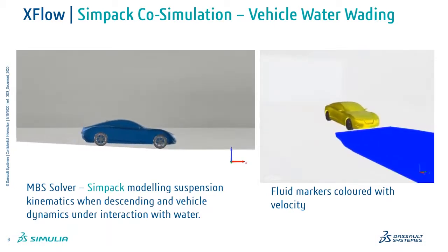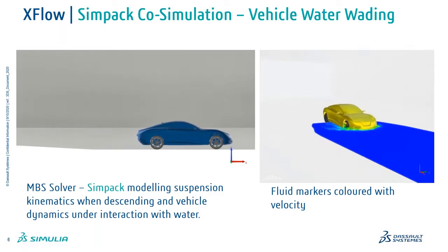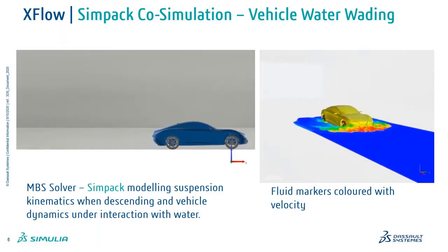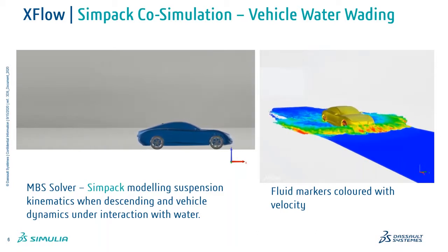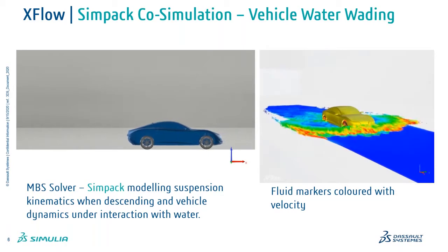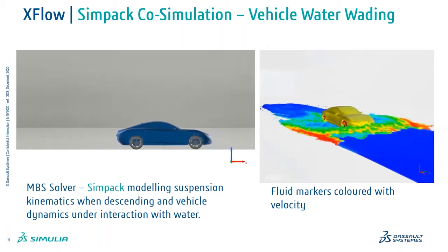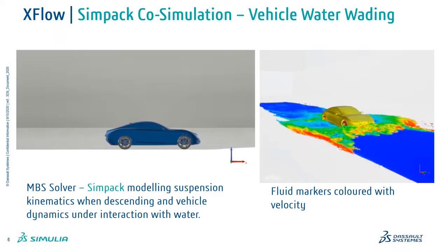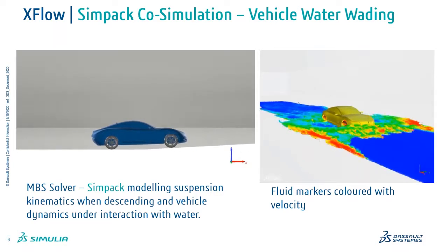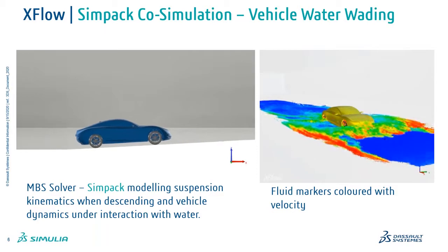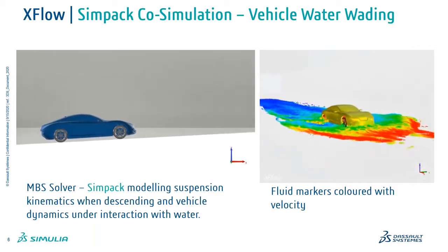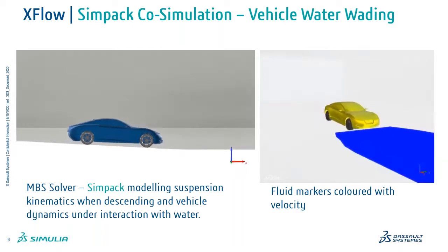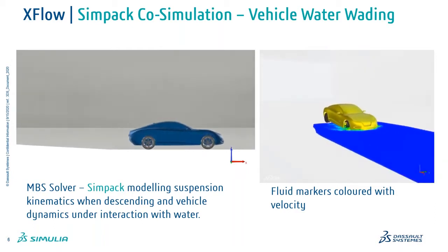So on the video on the left, you can see I'm not showing any fluid side. I'm not showing any graphical representation of the fluid, just the car entering the actual tank. What you can see here, this might be a bit complex on this video and the refresh rate, but you can see that the front of the car is slightly lifted up because of the force of the water, and you can see how the suspension is working when the car enters and leaves the actual tank because of the ramp, especially in this position here now.